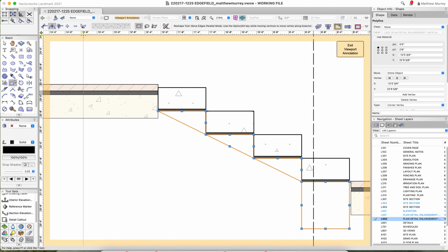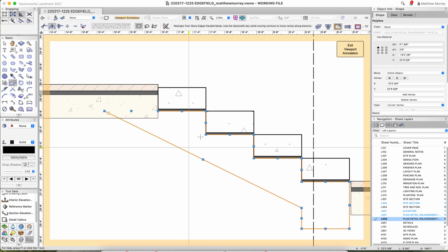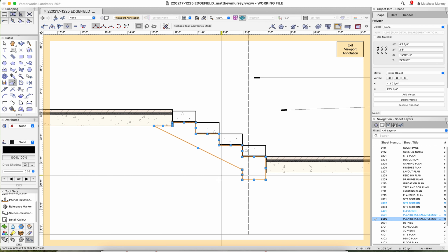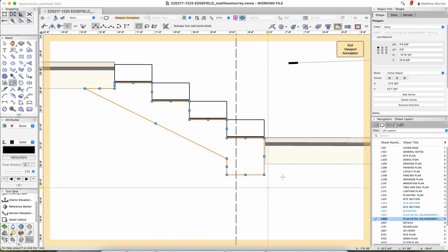And then we're going to use this, and we're going to pull this 6 inches, because I want to make sure we have 6 inches here for our concrete structure. Now we're just going to finish modifying this. We're going to pull that to that edge. Let's close this section, and we'll go ahead and take that to the corner like that. So that's the profile of our footing now.